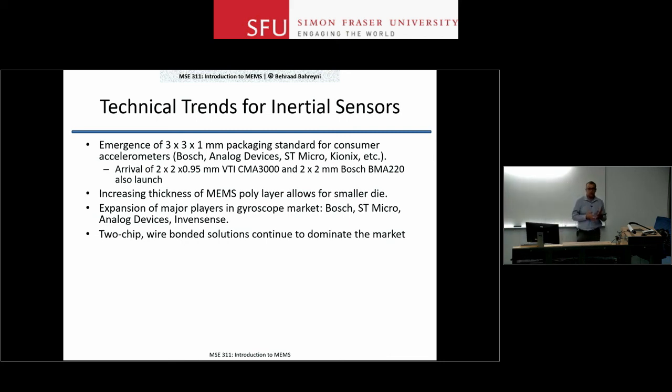The new thing on the block is that we want to have high performance accelerometers for seismic detection or for gravimetry, so where we can measure the gravity with, let's say, 6-7 digits of accuracy. And what that tells you is that if I have, let's say, a chamber of gas underneath my feet, or a nickel mine, or just regular rocks. This is important for what we want to do, mineral exploration on Earth, or if we want to do exploration of the moon and other places. We want to see what is underneath our feet without really having to dig.